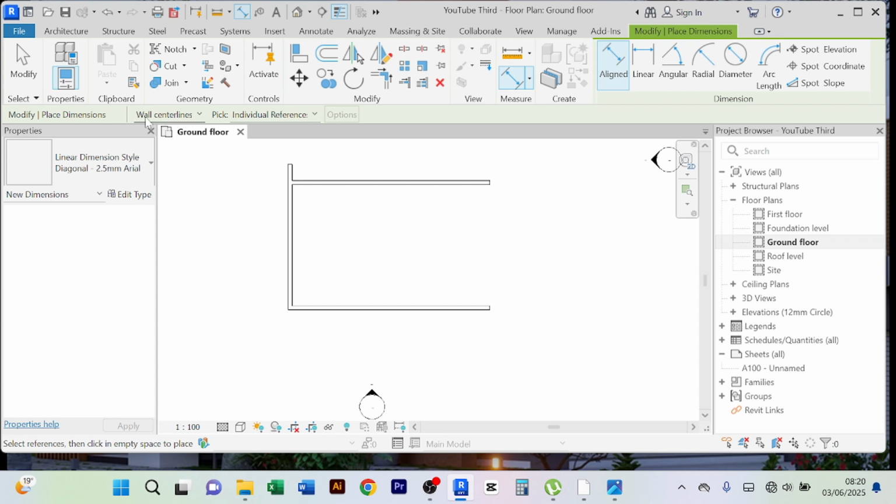So for us, we have wall center lines, but we don't want to measure walls from the center line. We want to measure walls from the faces, because that's basically what constitutes the space inside. If you measure wall center lines, your measurements start from the middle of a wall, which is not the correct case, because it can confuse you and give you spaces that may not be functional.